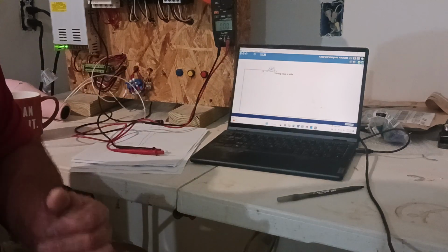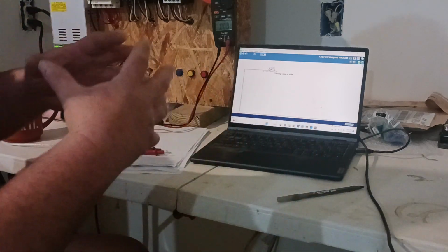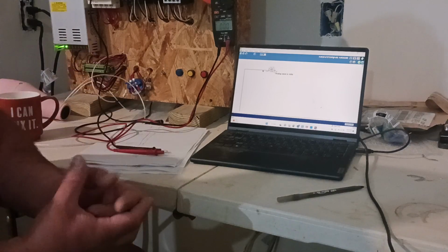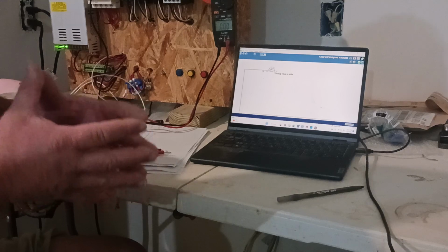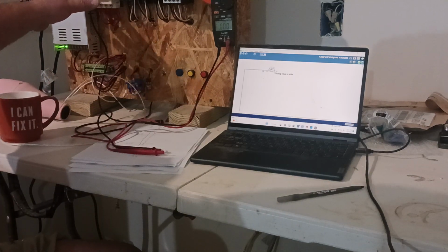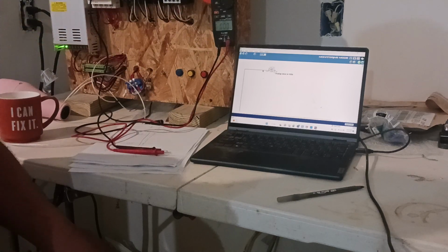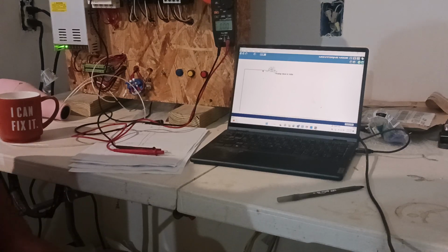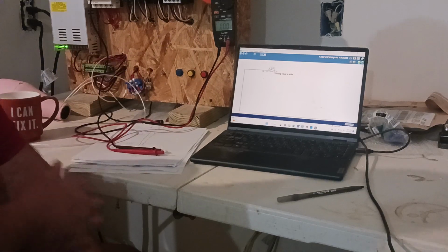Basically what that value allows you to do is, if you have the same range but more numbers within that range, it's called resolution. It's higher resolution. It allows you to pinpoint a value much more precisely. It's all about precision. This doesn't have high resolution, so the precision isn't great, but it's good enough for me to show you the basics. But you will see more precision with the higher resolution. The 16-bit channels, for instance, are over 2,000, so you'd have 10 times the resolution, basically.